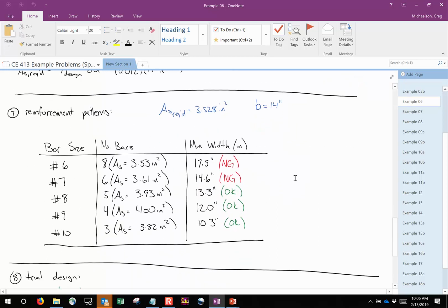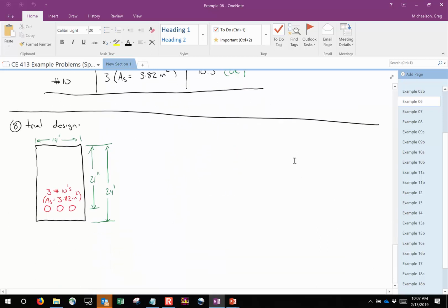Using the beam design aid in order to go through all of the permutations of areas of steel that would make sense, and then checking those permutations to see whether or not we can actually fit them in a single layer on the beam. When that was all said and done, we came up with 3 options that would actually fit, and we went with the one that had the least area, and so that's where we left off. And so now we have a beam. We actually have a beam that we can analyze.